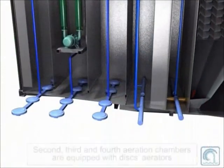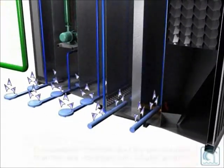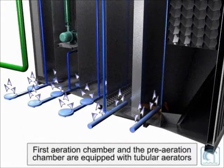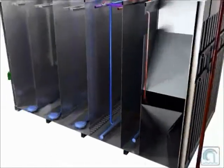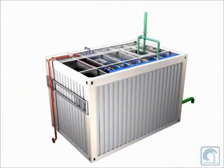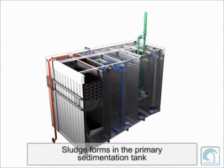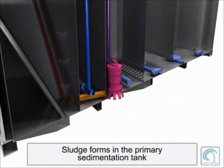The second, third, and fourth aeration chambers are equipped with disc diffusers. The first aeration chamber and the pre-aeration chamber are equipped with tubular coarse bubble diffusers. Inside the treatment plant, the sludge formed in the hopper bottom of the primary sedimentation tank flows by gravity to the sludge pumping station.